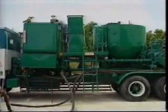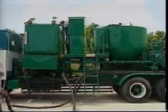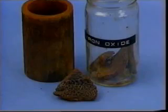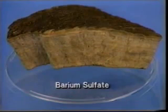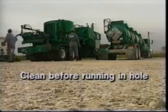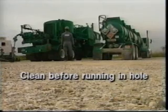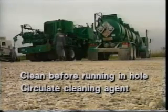Next, the condition of the tubing or work string should be checked. Whenever possible, the engineer should inspect the tubing or work string before it is run. Residual rust, scale, paraffin, sludge, and other debris inside the tubulars can be pumped into the formation and decrease well productivity. If the tubing is dirty, it should be cleaned before being run into the hole.